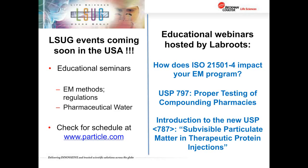But with the monitoring program, you would be looking really for changes in very key and high critical zones. And that again goes back to the difference between monitoring and classification, because classification is just a momentary snapshot. It doesn't look at the dynamic characteristics of the room, impacts of changes in the airflow due to changes or failure of a ventilation system,